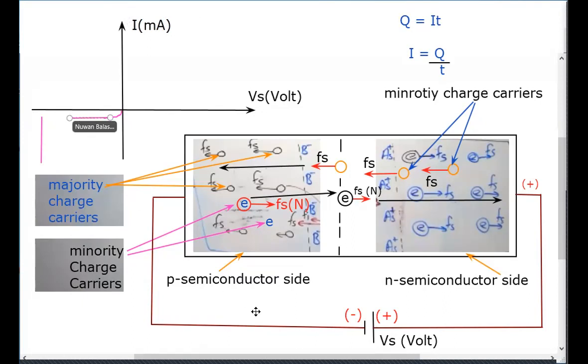No, sir, that is not possible. So when we increase the supply voltage, let me use some dotted lines, it may stay like this, but at a certain supply voltage the diode is burnt and a huge current flows through the diode. The supply voltage at that time is said to be the breakdown voltage, which is indicated by